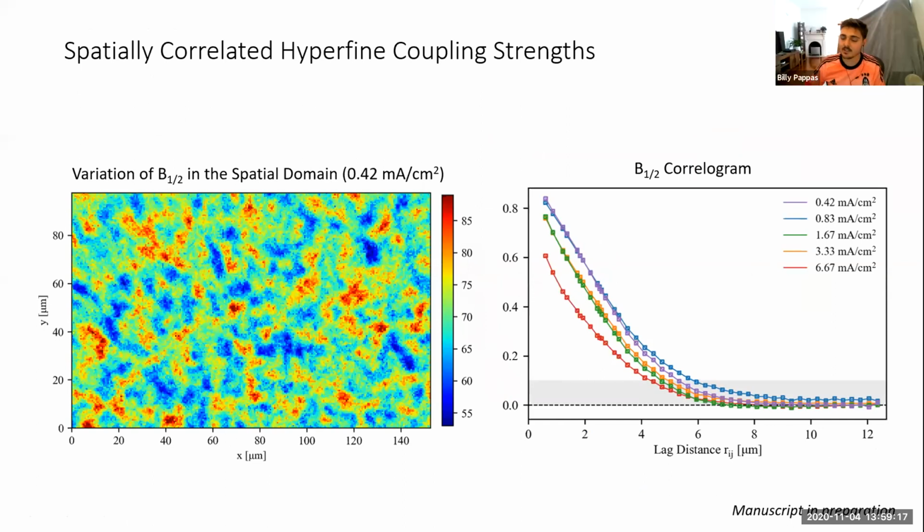There are several studies which have been done on ambipolar devices versus unipolar devices. And so you do get changes. The MEL changes drastically. Sometimes if you do hole-only devices, you get a negative MEL. And I think the reasoning behind that is you move from polaron pairs, which are opposite charge carrier pairs, spin pairs, to bipolaron pairs, which would be like charge carriers.